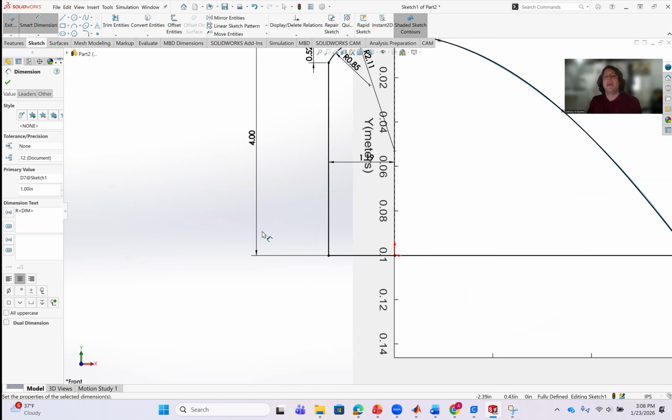Now we're going to make another section for this weir, and this one is kind of confusing. It's hard to explain unless you see the weir in person, or at least see the experiment in person. There's a large hole underneath, which we need to cover. Basically that hole allows us to put the weirs and fasten them to the bottom of the open channel lab. But we need to make an extended lip here so that the hole is fully covered.